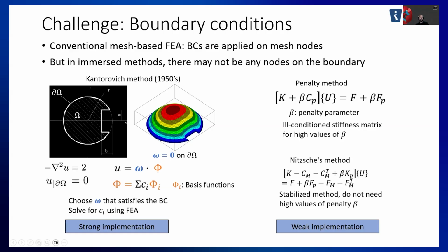So you're multiplying two functions here, right? Let's say your basis function is quadratic. Now you're multiplying quadratic with omega. Let's say omega is also quadratic. So now you're multiplying quadratic with quadratic, which means now your functions are fourth order polynomial, which means your quadrature should be much better, much higher than typical quadrature. So the requirement on the quadrature can cause errors, and that's a problem. It's a very elegant method, but there can be implementation challenges.